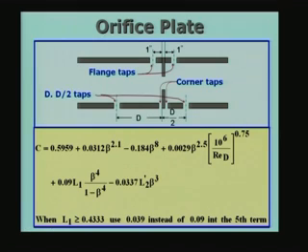And in fact, we have already looked at the differential pressure transducers earlier on. So, the choice of whether you are going to use a manometer or a differential pressure transducer depends on the maximum pressure difference you are going to encounter in a particular application. Of course, it depends on the velocity, the fluid and so on.